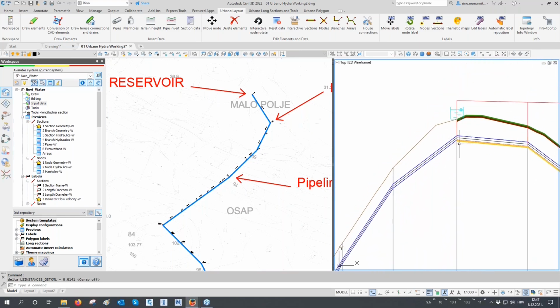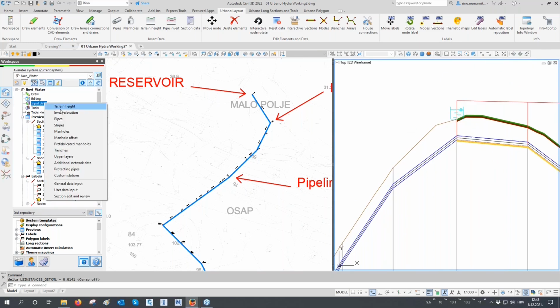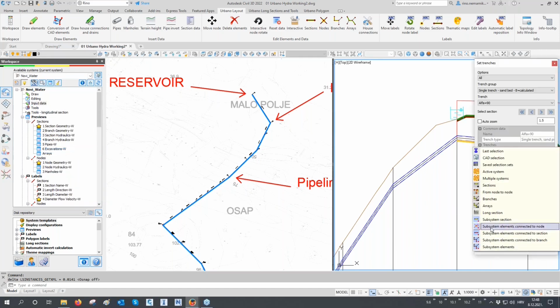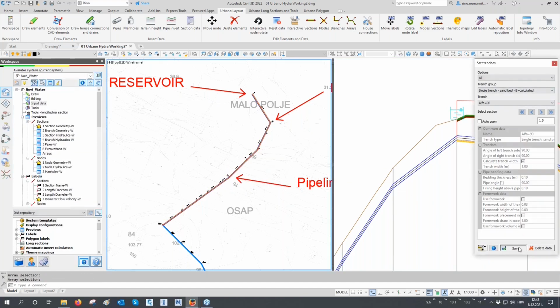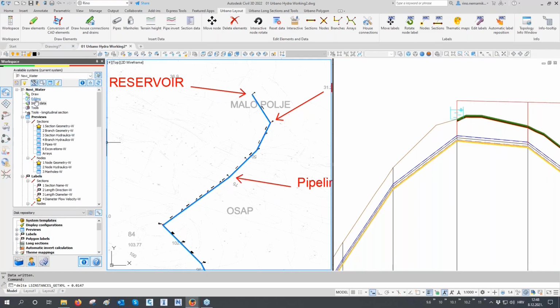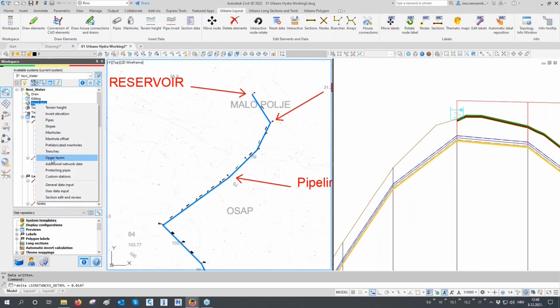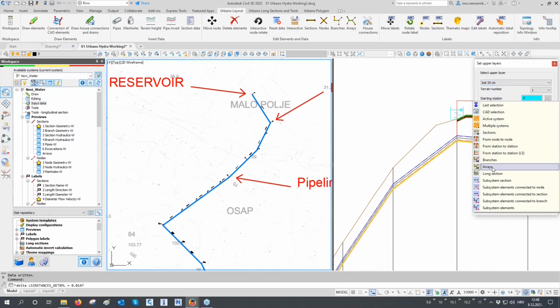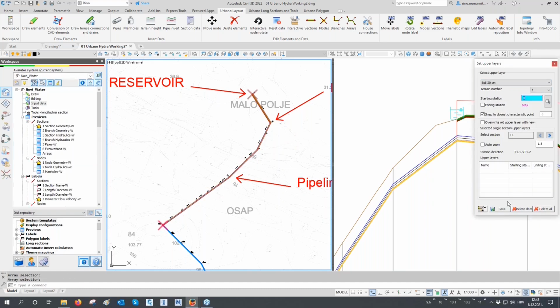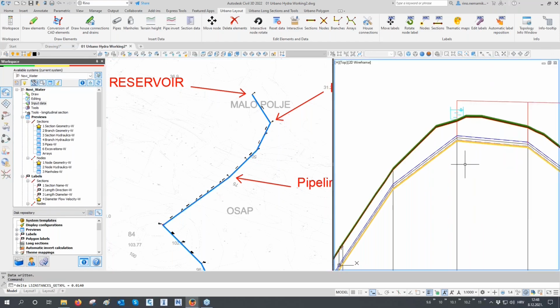You can see that we didn't set the trenches and the top layers, so we can set up that as well. Let's repeat from yesterday. Let's go to trenches. Let's select this array. Let's set the same trench as yesterday. Let's click save. Okay, let's go to setting of the upper layer. So input data, upper layer. I will use again the soil of 20 centimeters. Let's select this array and let's click save. Okay, and now we have everything defined.